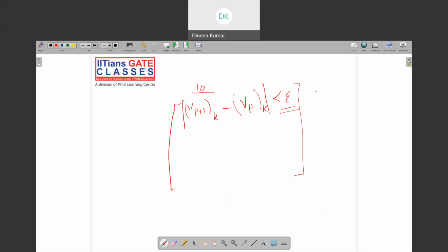In some buses, what you are specifying is Q. Now from the voltages that we are getting, we have to find the Q. So Qk will be minus the imaginary part of Vk star times the sum over n equal to 1 to n of the current, so Ykn Vn, right?